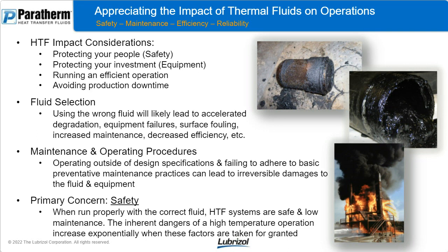So fluid selection is a very important part of that. That's why we have a whole section based off of it. We're not talking about brands of fluid here. We're not talking about any of that. We're talking about just the right design fluid, a purposeful, intended fluid to be used specifically for heat transfer, right? So we'll go through what the hallmarks of that are. Because using the wrong fluid is likely going to lead to premature accelerated degradation. That in turn is going to cause more potential for equipment failures.